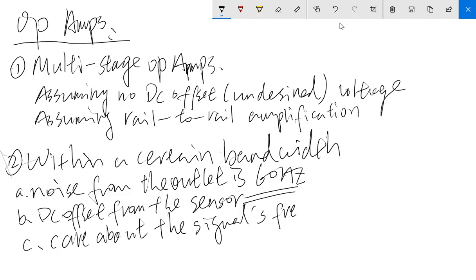So feel free to use a 3 something Hertz to filter out all signals higher than that frequency, right? So for example, if I change the frequency to something above 3.4, what kind of parameters you want to pick up? Right? Just tweak the parameters of the capacitor and resistor to make it work.